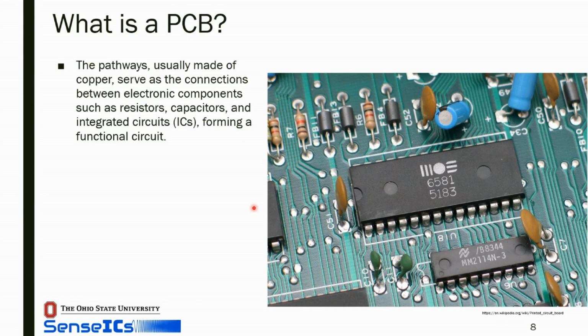At the end, it's a protective layer, as you said, to cover that copper because copper oxidizes really quickly. If you left the copper exposed, it would turn green and it would be hard to solder to that. So the green stuff that you see is a protective covering for the copper. And you can see where you do solder joints, it's silver because there's solder there. There's no solder mask in the location where you would need to solder.